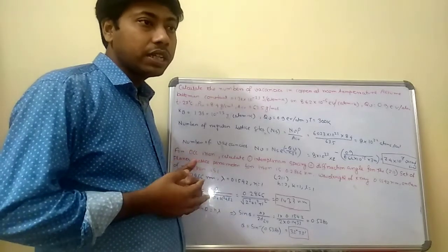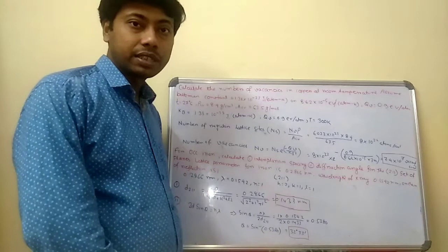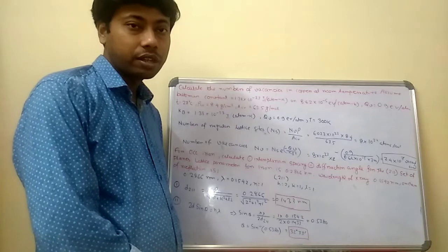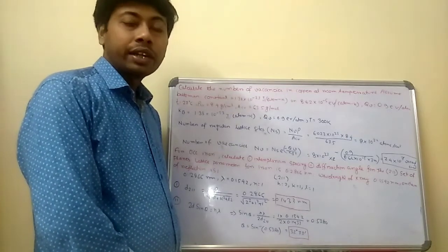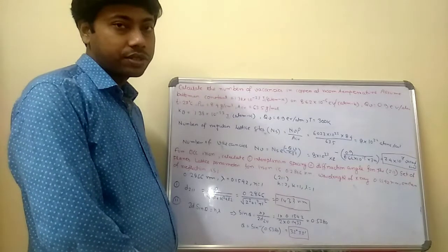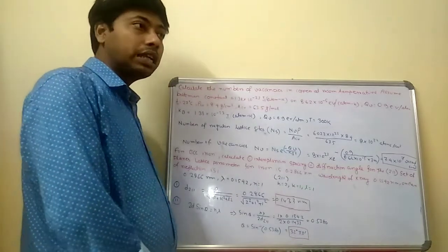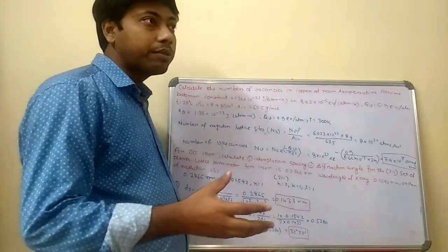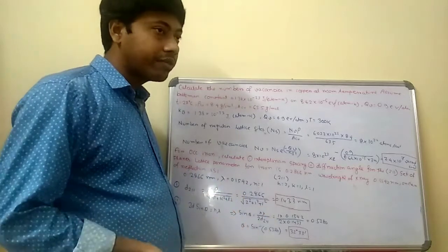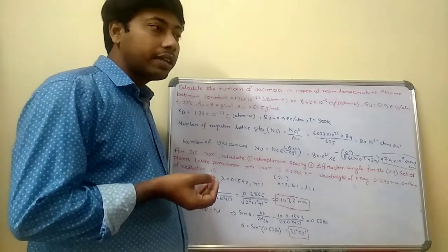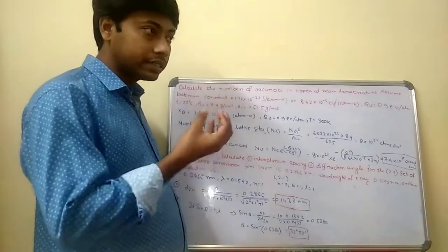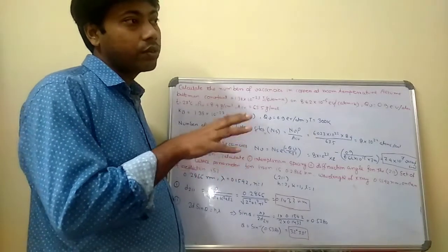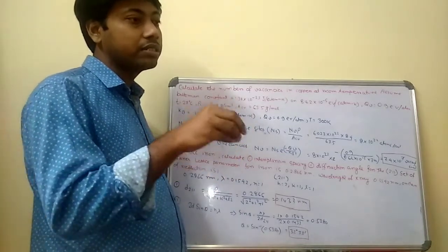As you know, there are different types of crystal defects in a particular material, like point defect, line defect, surface defect, and volume defect. Point defects include vacancies, substitutional defects, and interstitial defects, as well as others like Frenkel defect and Schottky defect. These are zero dimensional defects, and that's why they are called point defects. When atoms are missing from a particular location of the crystal structure, this type of defect is called